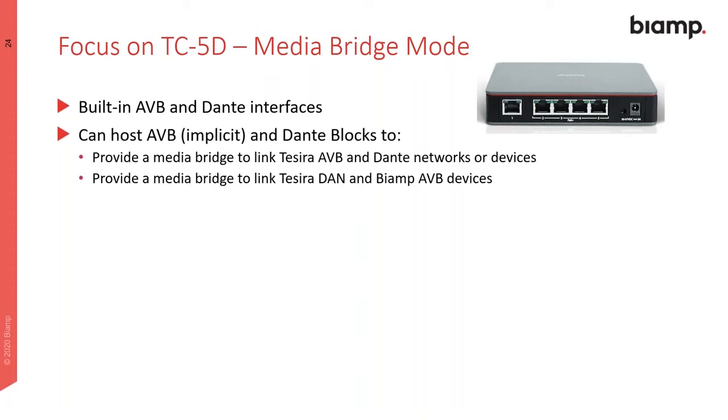So anytime you connect a device with AVB connectivity, it will automatically detect and configure this port to be the AVB part of your system or the Dante part of your system. And it provides a media bridge to link the Tesira Dante and the Biamp AVB devices. So you can look at it from that perspective as well.